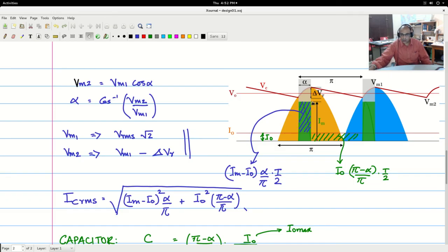Average value through the diode will be, you see that through every diode it flows through alternate cycles. So through D1 and D4 it will be through this. D1 and D4 again it will flow in the next yellow half cycle. D2 and D3 it flows here, and D2 and D3 will again flow in the next blue half cycle. So therefore the average for this is Im, duty cycle will be alpha by not pi but alpha by 2 pi, because this repeats every 2 pi.